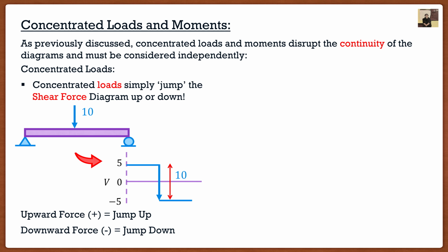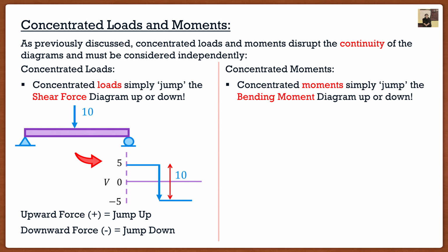Now here's where things get a little bit tricky. Just a little bit, but again, you guys are super smart. Won't be a problem. Concentrated moments. Now, these are almost identical to concentrated loads, where a concentrated moment will simply jump our bending moment diagram up or down. So concentrated loads impact our shear force diagram. Concentrated moments will impact our bending moment diagram.